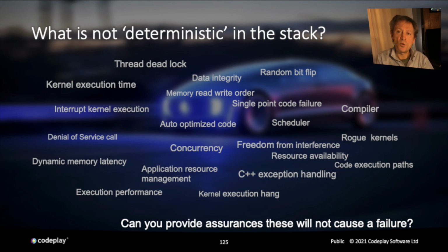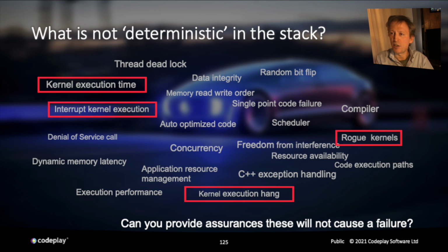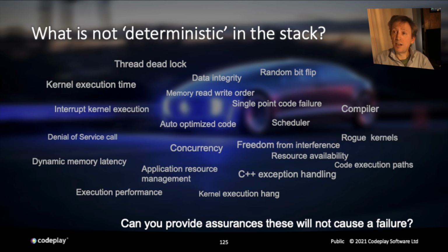We also have the issue with how kernel execution is managed. How do we manage rogue kernels that do not finish execution? How can we interrupt kernel execution and not enter an indeterministic state? And lastly, and this is very important, wherever in the specification you see the phrase "behavior is undetermined", this is a red flag to the ISO 26262 safety standard, and it must be rectified such that the indeterministic is made deterministic.